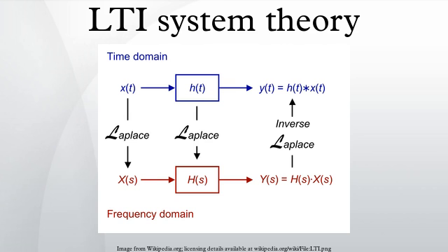For all LTI systems, the eigenfunctions, and the basis functions of the transforms, are complex exponentials. That is, if the input to a system is the complex waveform A_s e^{st} for some complex amplitude A_s and complex frequency s, the output will be some complex constant times the input, say B_s e^{st} for some new complex amplitude B_s. The ratio B_s/A_s is the transfer function at frequency s.